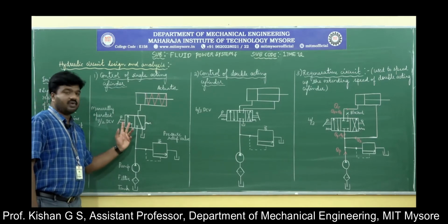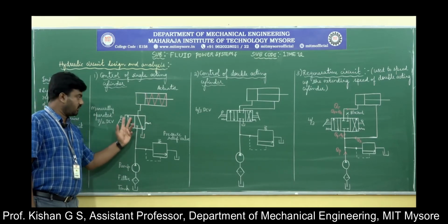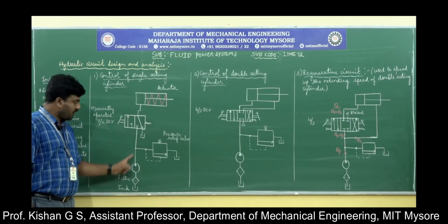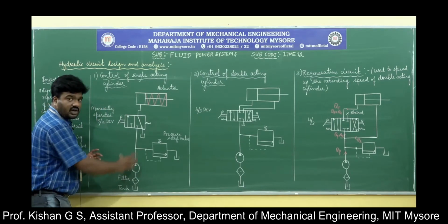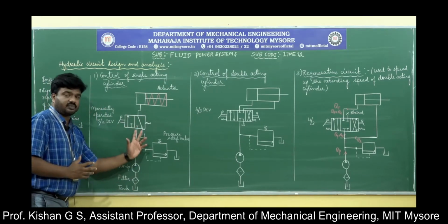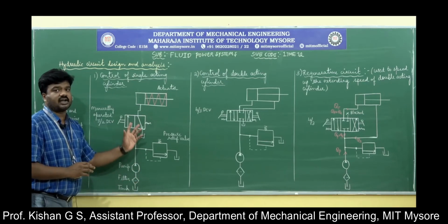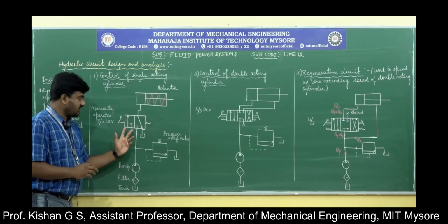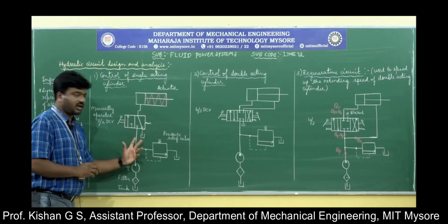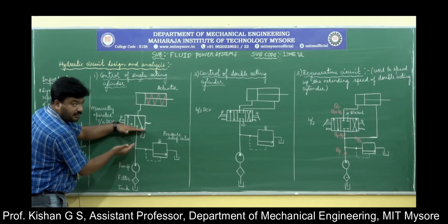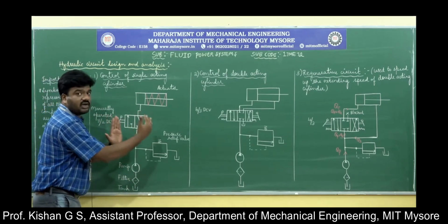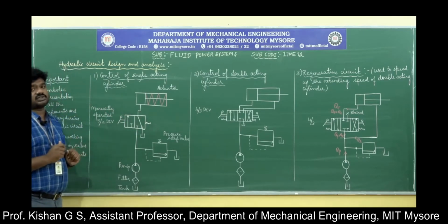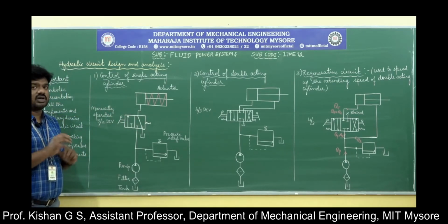Okay, so here the valve works at 2 positions. One is at position 1, wherein there will be a flow from the pump port to the system port. Observe carefully here. We have represented the fitment to the second envelope. That doesn't mean it operates only in the second envelope. It means that it operates in the first envelope as well as the second envelope. Whatever we fit here up to the direction control valve accounts for each of the envelopes, or each of the positions at which the direction control valve is being considered, for the entire operation of that particular actuation system.